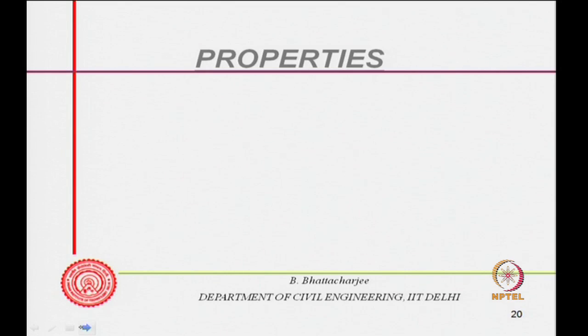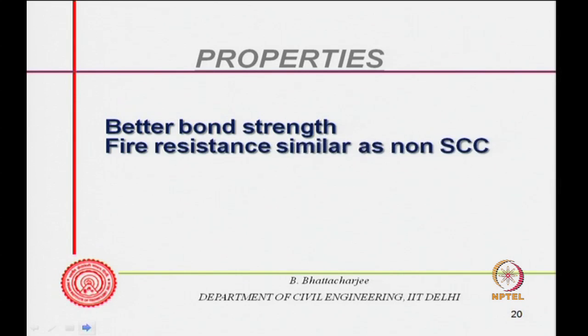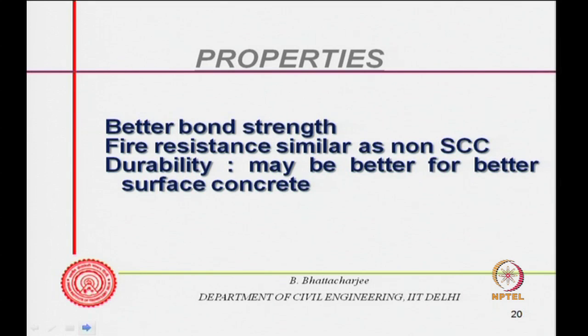So, better bond strength, more paste could give you better bond strength with the steel. Fire resistance will be similar to non self compacting concrete, and durability may be slightly better because of the better surface concrete.